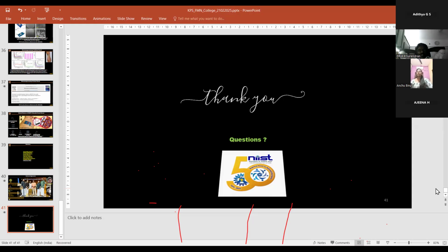But polymer is a low melting material, whereas ceramics can go to very high temperature. If you are using a sensor made of a ceramic material, up to maybe 1100 or 1200 degrees it is okay. For example, PZT and barium titanate are high temperature stable materials.